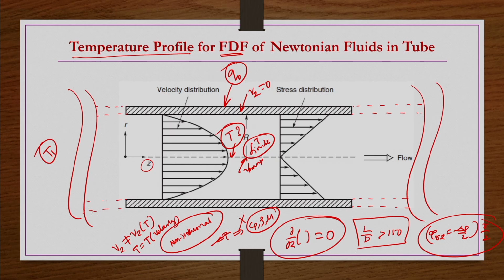Fine. So, now three conditions are there for temperature. So, we have to find out. Another most important thing: for the velocity profile in this fully developed region, we found that it is a function of R only, right, and then accordingly we got the velocity distribution, and that is true also if we have one dimensional laminar flow.